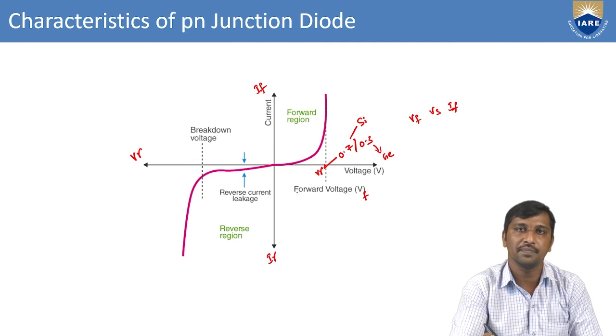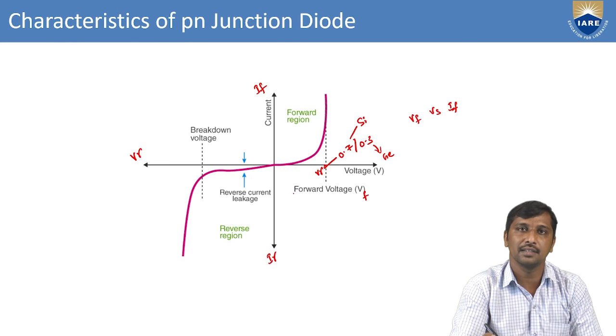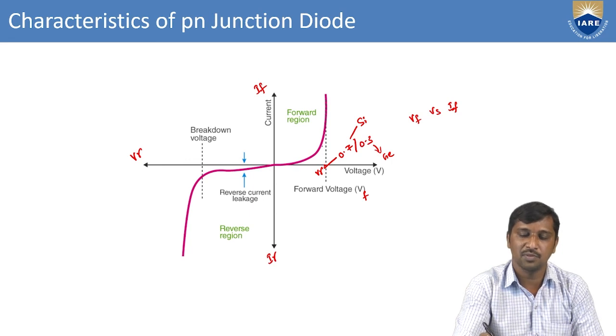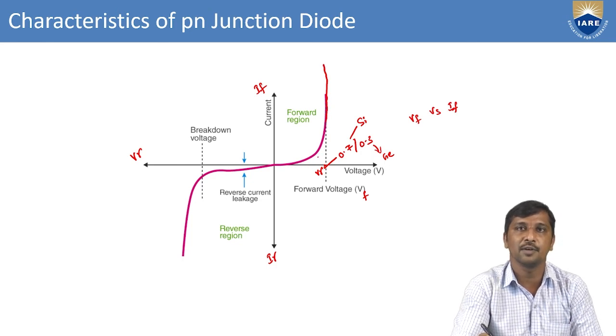What happens under the forward bias operation? It reduces the potential barrier region between the P and N side junctions. Hence, more charge carriers diffuse from one region to the other, and maximum current flows across the PN junction. So whenever the applied input voltage just crosses the cut-in voltage, the conduction rate increases. That is the reason I drew the curve like this.